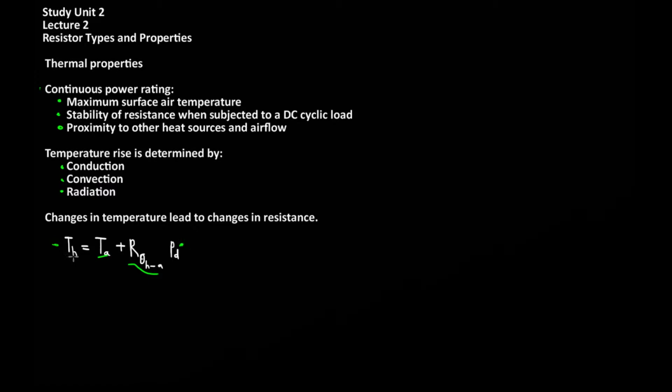The maximum hotspot temperature is limited by the ambient air temperature as well as the average power dissipation and the thermal resistance between the hotspot and the power dissipation. If the air temperature starts to increase, this decreases the average power which can be dissipated in order to not approach a hotspot temperature which would result in a failure in the device. Once the hotspot temperature approaches the air temperature, the allowable power dissipation will decrease to a point which approaches zero. In other words, no power can be dissipated in the resistor as the ambient air temperature approaches the maximum hotspot temperature.